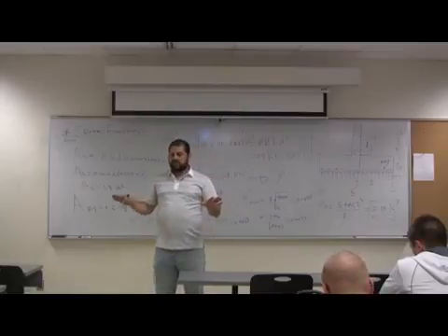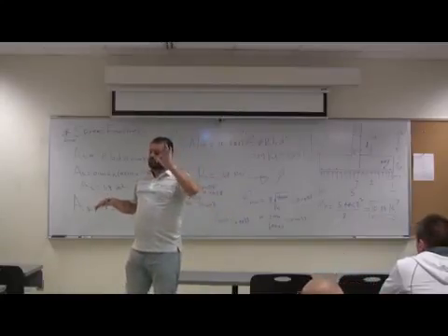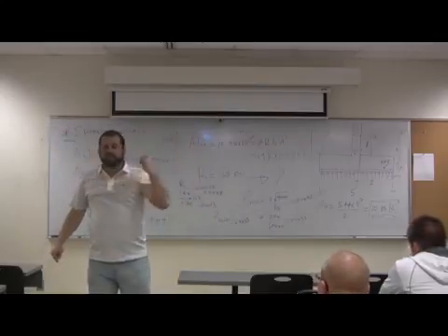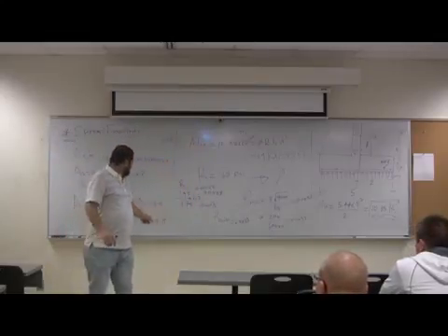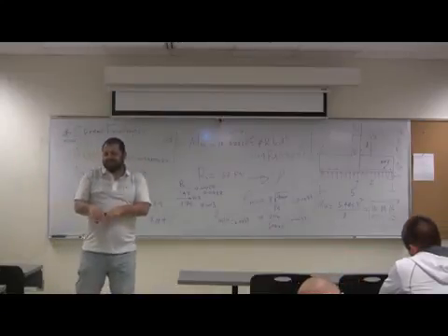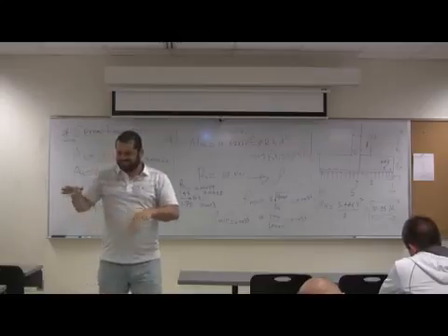6 spacings. So 4.5 times 12, that's the width in inches, divided by 6. So this will be number 4 at 9. Don't worry, just tell the guy to put 7 bars. Some spacings will be 10, some will be 9, some will be 8. Not a big deal.